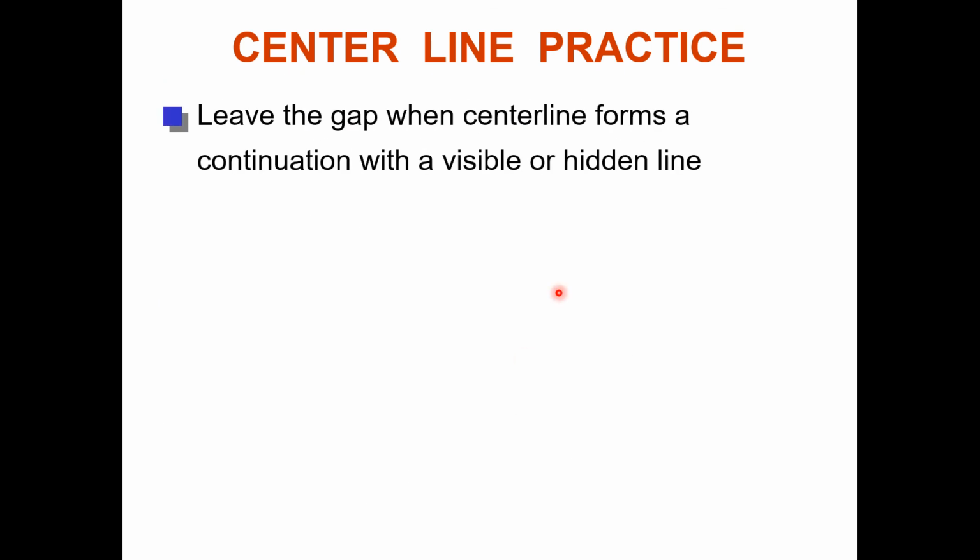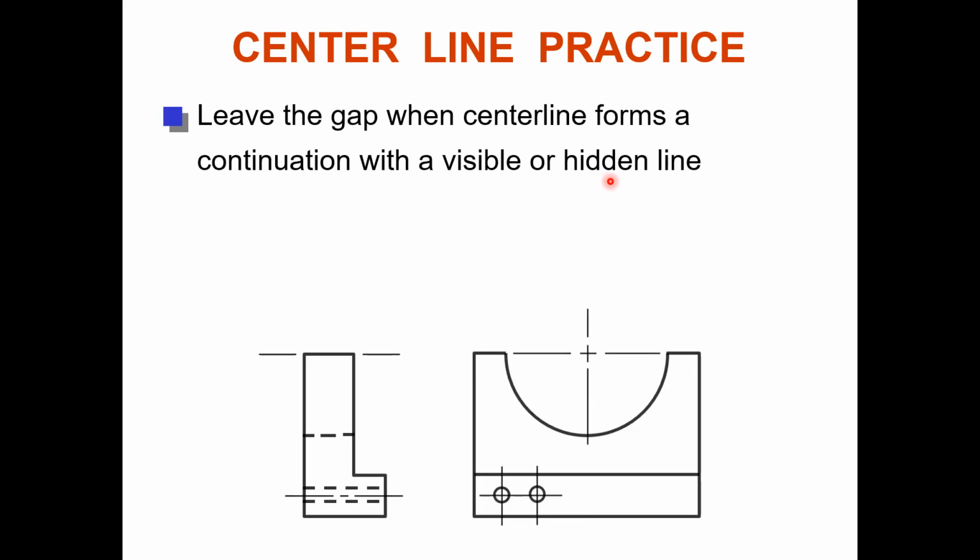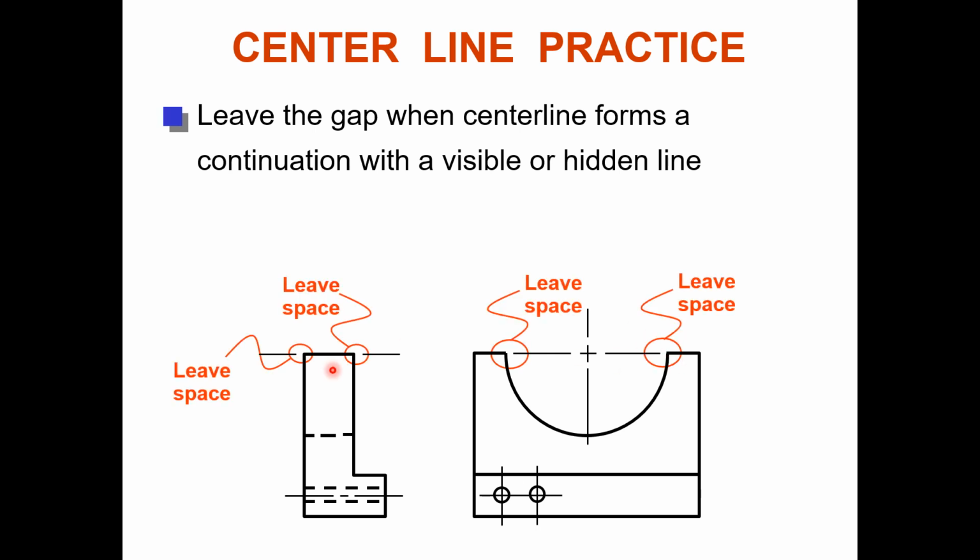Leave the gap when a center line forms a continuation with a visible or a hidden line. Here you can see that is a center line and that is a visible line. You should leave a space from the endpoints. Leave the space.